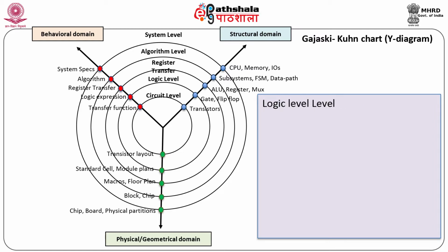Register transfer level. In this level of abstraction, the basic building blocks are some simple registers and data routing elements like multiplexers. Register transfer describes a design methodology in which the data is transferred between storage registers and other logic units. Communication signals are frequently grouped together and interpreted as either unsigned or signed binary state.